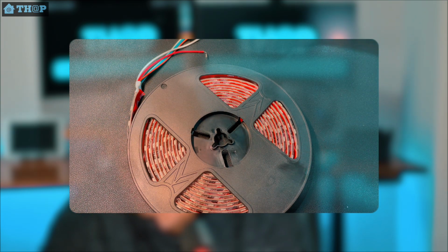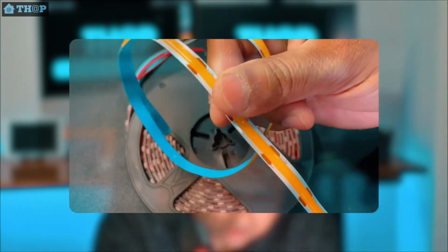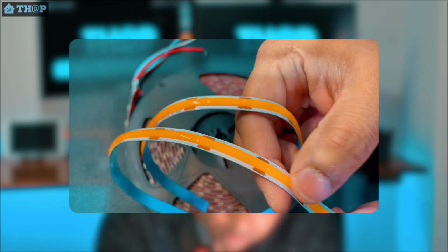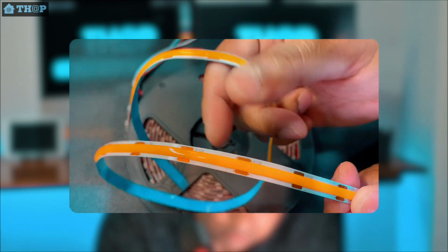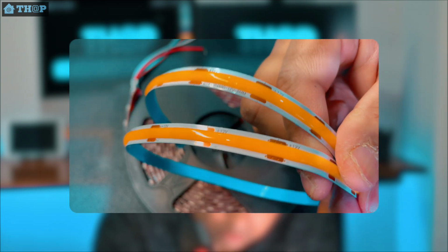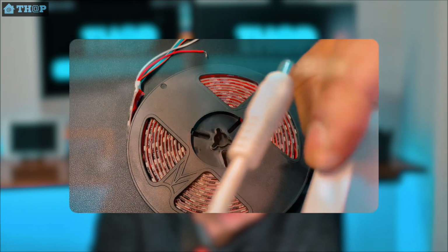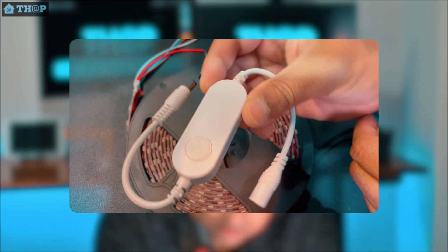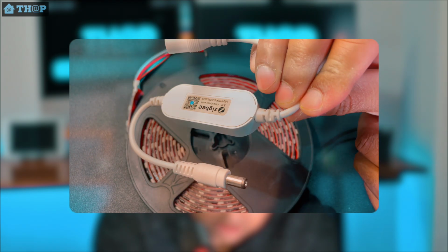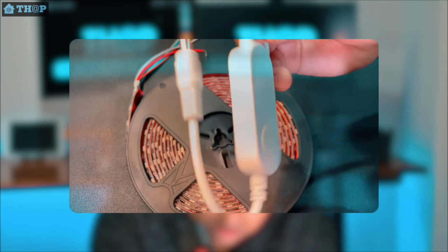Another version of these LEDs are these COB based LEDs, as they are called. This is also a 12 volt LED, and this is also an analog one, but it gives a better diffusion of light. Basically you don't see those annoying dots when you use this kind of version. This is very common for under cabinet lighting and kitchen lighting, and these are simple on off kind of controllable LEDs. You could use a smart controller like this one I have here. This is the Zigbee LED controller, and I can change the time and the color. If the LED strip supports color, you could change the color also with this